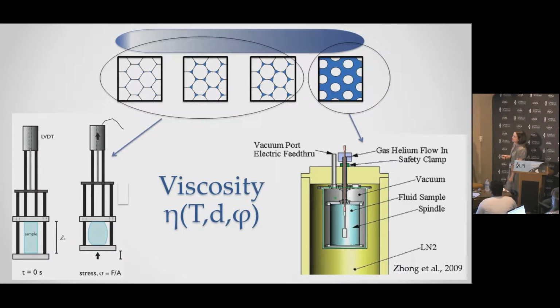So viscosity can be measured in a couple of different ways, depending on the amount of solid that you have. And this is the world that I feel comfortable with. These are the kinds of experiments that I've done in the past, where you basically take a mostly solid sample and you squeeze it between two plates very slowly at controlled stress, and you measure the strain rate over time.